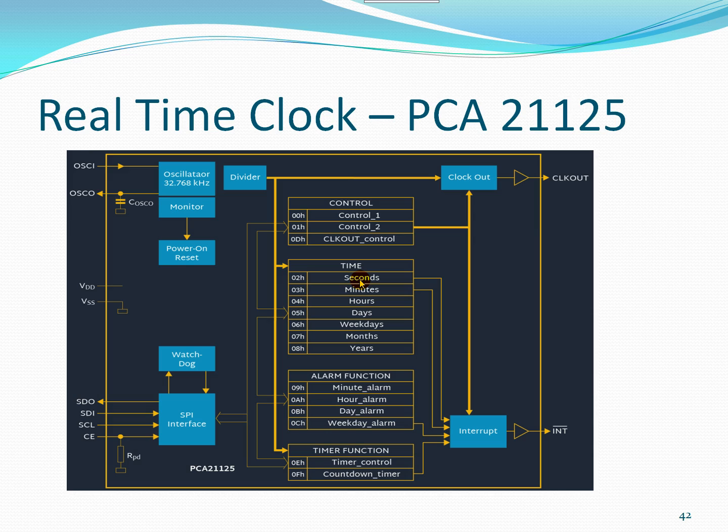So that time tick will be given as an input to this memory block, or the software timer block. That software timer will update the clock ticks into seconds, and if 60 seconds have finished, the minute will be updated. If 60 minutes have finished, the hour will be updated. If 24 hours have finished, 1 day will be updated. Likewise it goes on up to the years.